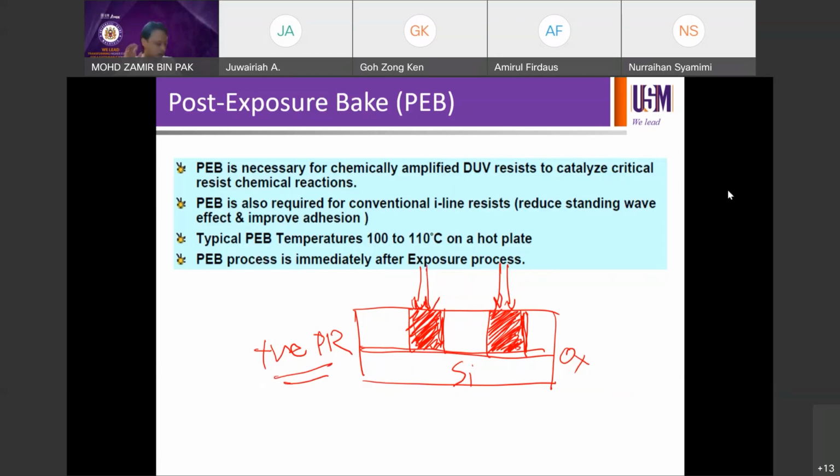You have to understand that, that's the very basic one. If you're clear with that, then the rest will be okay. So exposed positive resist, exposed soluble; negative resist, exposed hardened. In this case, we expect the shaded regions to be soluble later on. Not yet, because we've only just done PEB. If you revisit the 8 steps, PEB comes before development, right? CED. Now we're only at step E.